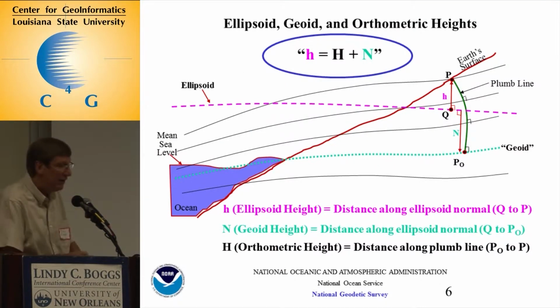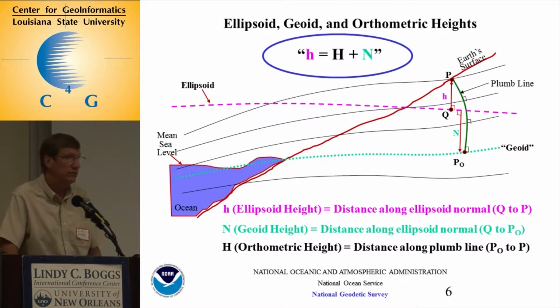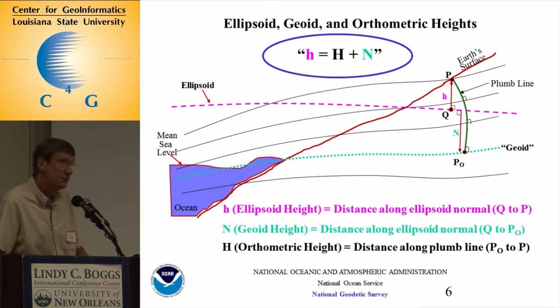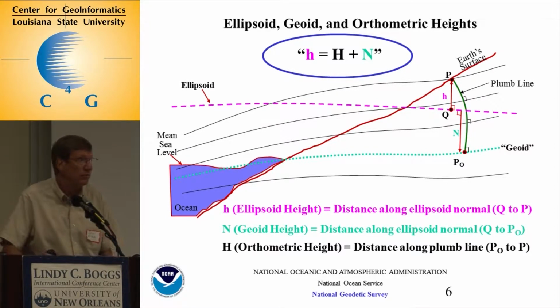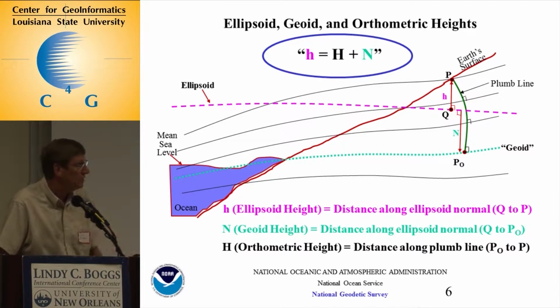So in this diagram here, a very simple diagram, we talk about the geoid. This is the surface that we're saying we're referencing all our heights from. All of our orthometric heights are referenced to that. And that's not something that you can just dig down and see, a little blue line going through the country. You can't have a geoid meter to go out there and just measure it and say the geoid height's this.